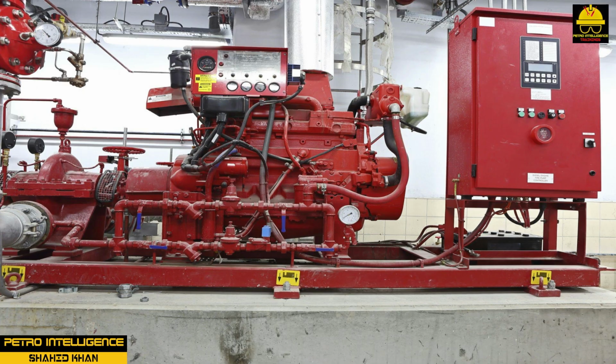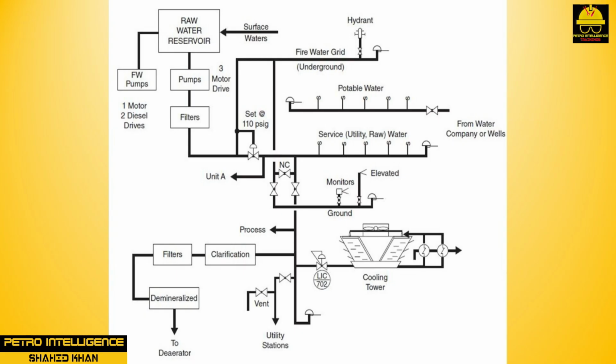Fire water is supplied to the plant by pumps, which must be capable of continuing to run if power to the plant is lost. These pumps are typically diesel-driven to ensure operation if electric power is lost. The FW system pressure can be supported by cross-connecting from the raw water system. Note that operations at some plants can differ greatly from those described in this course.